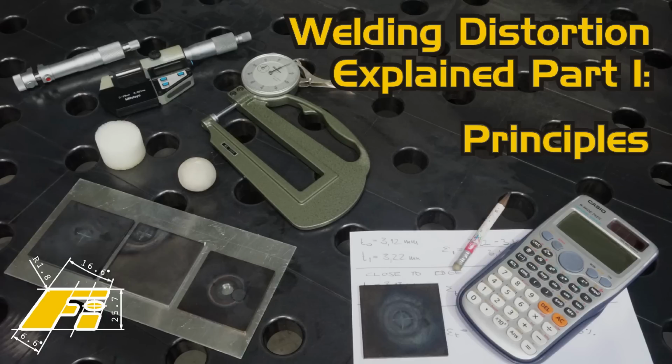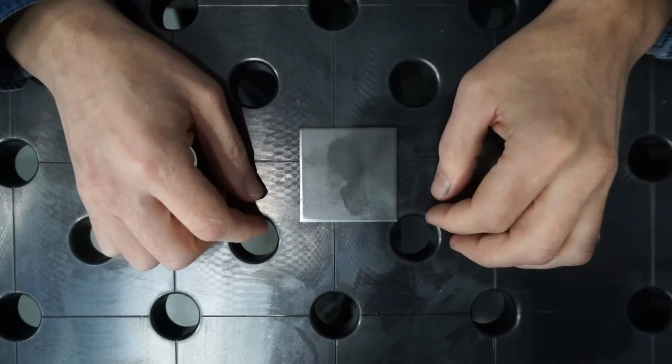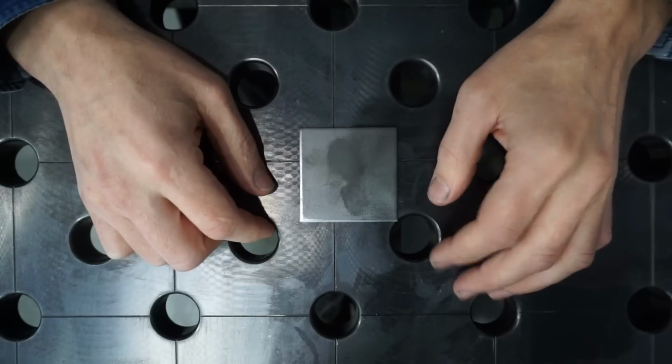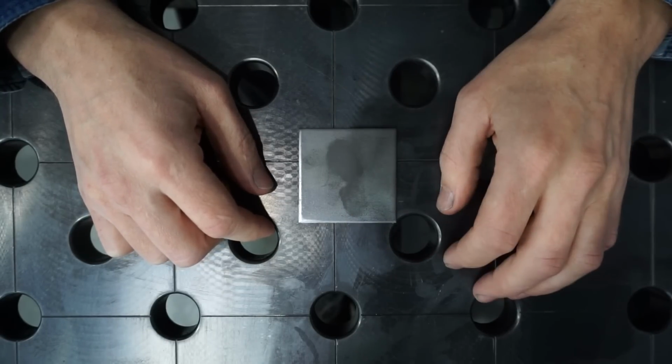Distortion of welded components can be hard to forecast, in some cases even qualitatively. But let's not start where it gets complicated, rather let's first study the primary mechanism of welding distortion with the simplest experiment possible, which is the single heated spot. Weld beads can be understood as an array of heated spots. Of course, in a weld bead they do interfere with each other and change the situation a bit. However, the mechanism in weld beads is qualitatively the same as with the single heated spot.